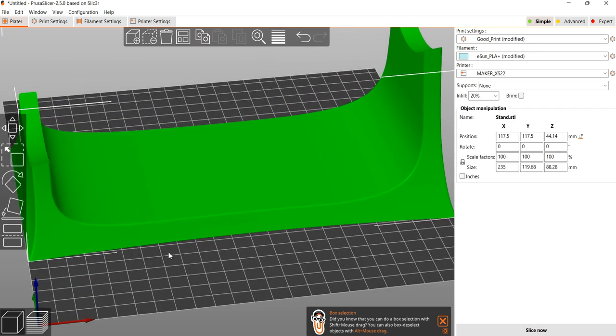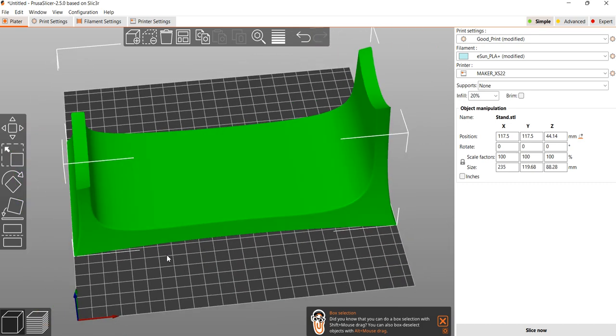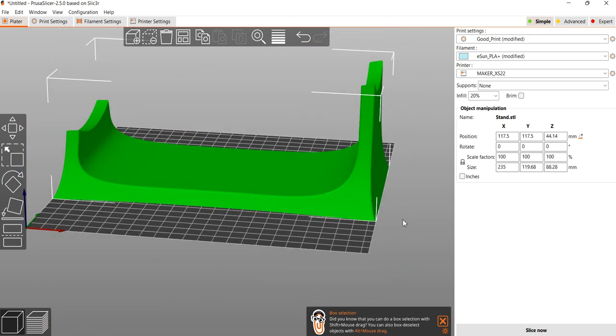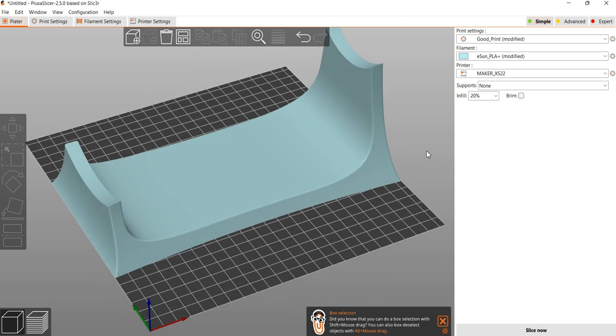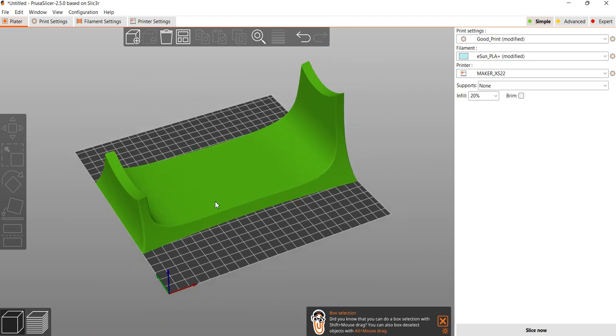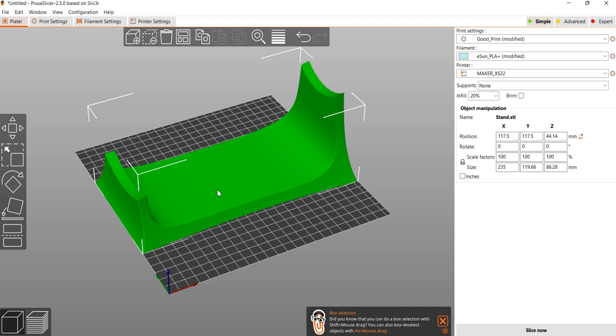Now you can see this is the printing bed. The nozzle will be out of the print area. So we can't print this object on this bed. So we have to cut it in two parts and print it on the bed. Select the component. Here we can see the 5 options: move, scale, rotate, place on face, as well as cut.